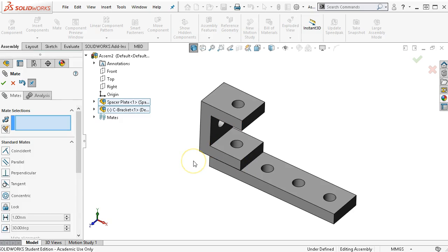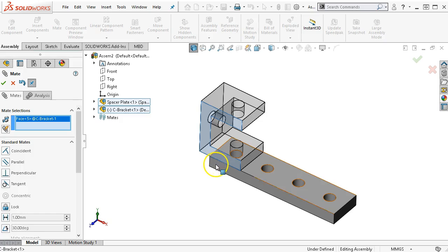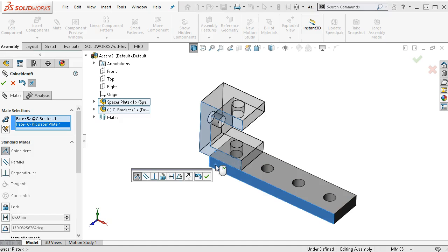There are times where we want dynamic, in which case we leave one of those items just because we do want it to be dynamic. We want to see it move. Alright, so the choice here would be, do I leave it coincident? Well, looking into my design intent, it could happen that this would need to grow or shrink, in which case the coincident isn't really my best choice here. The staying coincident face to face is good. The concentricity between is going to stay on center.